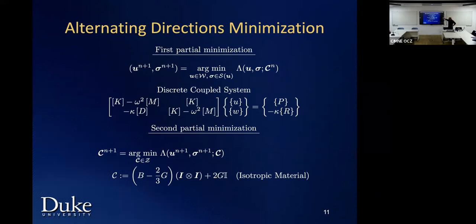I just discretize it and put it in an algebraic system. This is something that you'll be very comfortable with. What you see on the diagonal is a Helmholtz operator, stiffness and mass. Sorry, change of notation here from different presentations. That was gamma before, that's omega, the frequency. A stiffness matrix, again the same Helmholtz operator. And this D is what we call the observation operator. This is what connects data to the model.